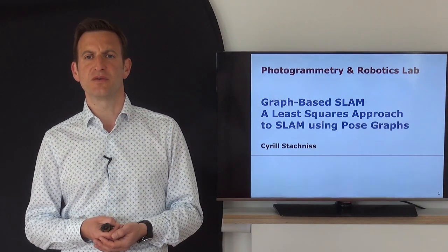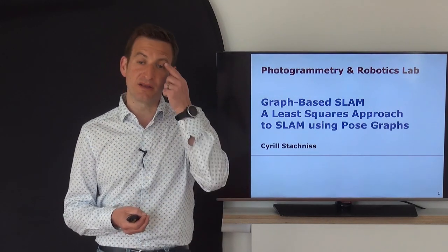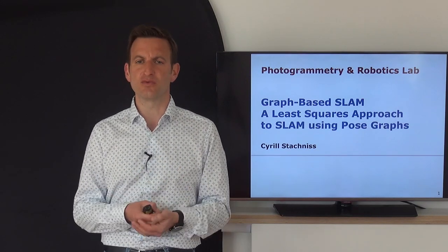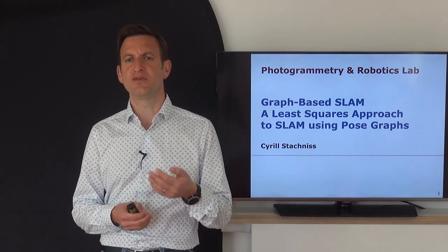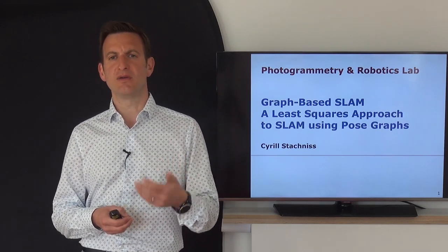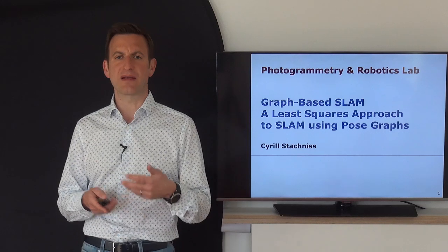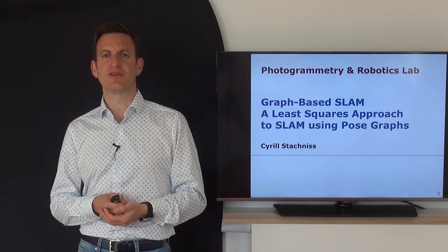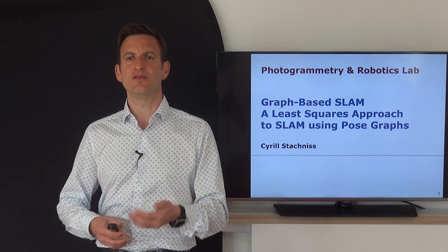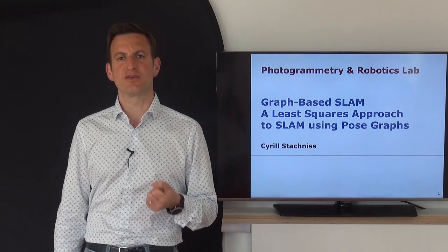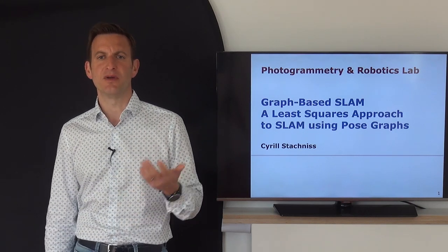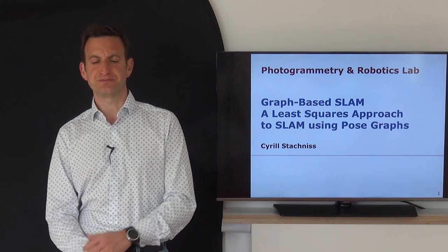So most of those systems which build maps of the environment which have a certain size, so which are not, let's say, a single room or something like this, typically use a graph-based or pose-graph-based SLAM approach in the background in order to correct the poses and build a consistent map of the environment. And the goal of this lecture today is to introduce you to these graph-based SLAM systems so that you are in the end able to build your own system that performs the optimizations in here.